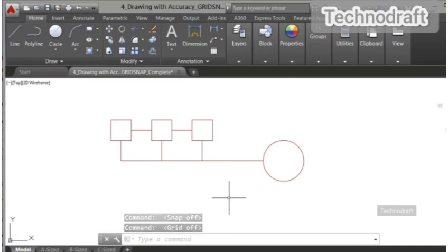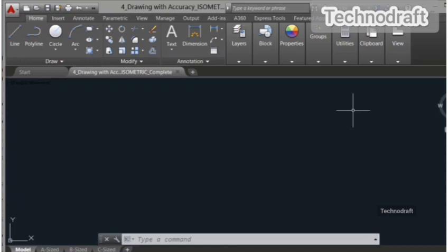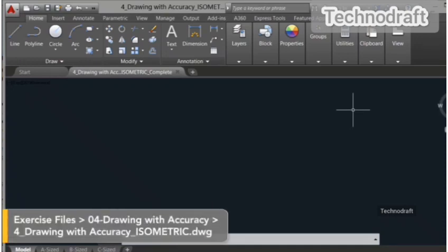And the good thing is, if I now switch those off, if I switch off snap to grid, there is my lovely flowchart, all neat and tidy and regular, because I have used those one unit squares to space everything out nicely and tightly. So that's how you use your grid and your snaps in AutoCAD. Again, practice in preparation to become an AutoCAD professional.